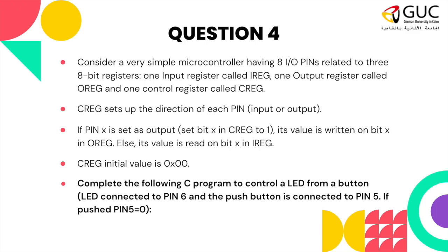This microcontroller has 8 I/O pins related to three 8-bit registers: one input register called the I-reg, one output register called the O-reg, and one control register called the C-reg. So it has the same concept as the Atmega. Here the I-reg corresponds to the pin register, the O-reg corresponds to the port register, and the C-reg corresponds to the DDR register. Okay, but this is a different microcontroller.